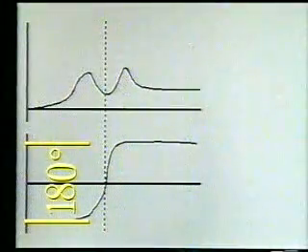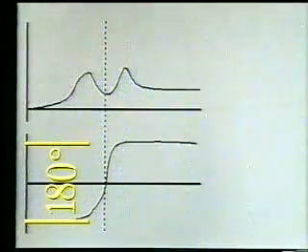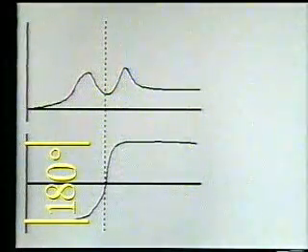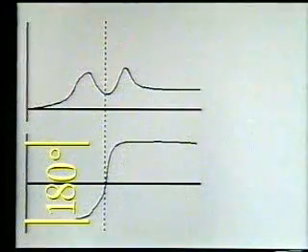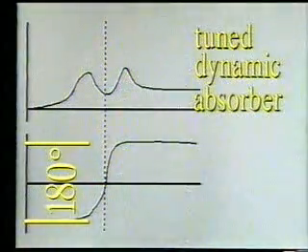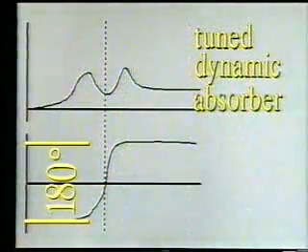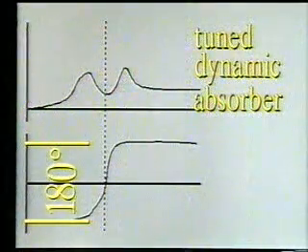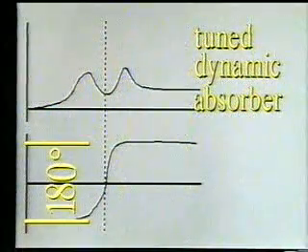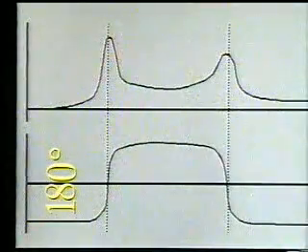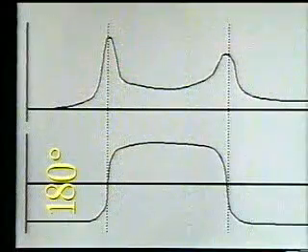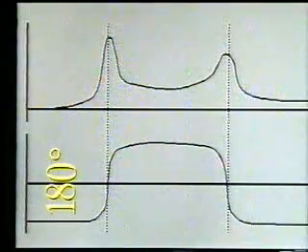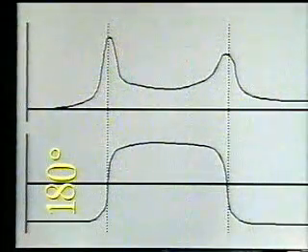However, the amplitude versus RPM data does not have an increase at that frequency, but may even have a low area or hole. This indicates the presence of some mechanical damping, such as a tuned dynamic absorber. The dynamic absorber is designed to remove the vibration at a particular frequency, and this indicates it is doing a good job. When there are two phase shifts, it indicates there are two resonances in the system. Both phase shifts will be in the same 180-degree hemisphere.